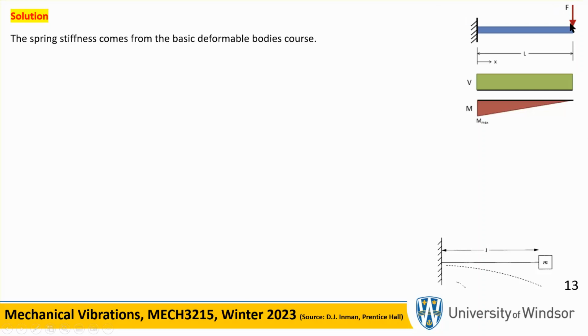So if you have a cantilever beam point loaded, the shear force is constant because you make a cut anywhere, the force that balances F is F, okay? And moment is maximum at the wall because it's F times the distance as you cut, so it's going to be linear. The maximum bending moment is at the fuselage, at the wall, because that's where the moment is maximum.